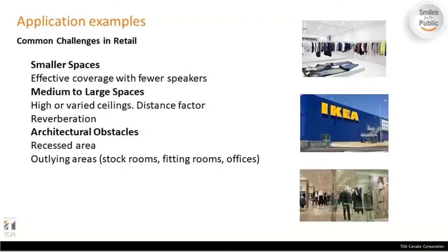Yes, so now we'll be talking about some application examples. Common challenges in retail, right? If it's a smaller space, the small challenge that everybody faces is the effective coverage. Because it's a smaller space, you don't want to spend a ton of money. You don't want to suspend speakers everywhere you look, right? You enter the space and all you see is speakers, speakers, speakers. The client doesn't want that. The customer doesn't want it. So you have to be careful while designing a small retail space to give maximum dispersion, to give maximum intelligibility